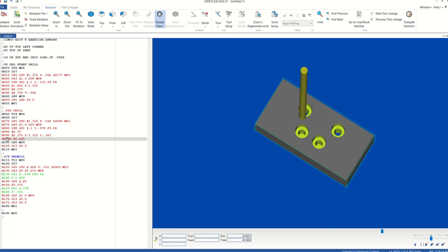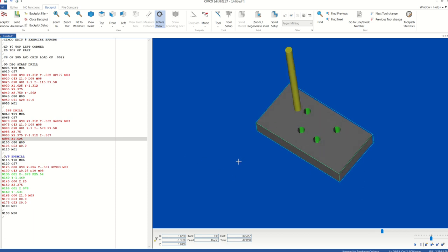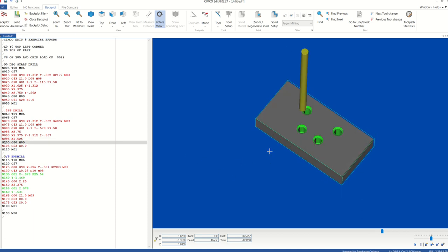And as you can see, there is a tiny, tiny difference between what is a 0 and what is the letter O. Letter O's are perfect circles. Number zeros, they're oblong, okay? So that is why that was giving me that little mini seizure moment there on my part where the drill was just going down and up. It's because it was reading this and it was giving me an error on that command line. So now when I drill this and I move through manually, you can see it's now drilling that whole location, okay?